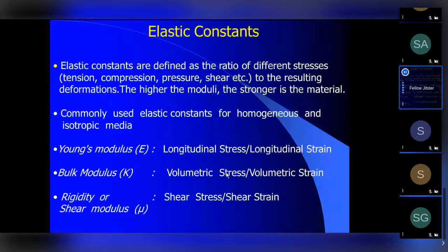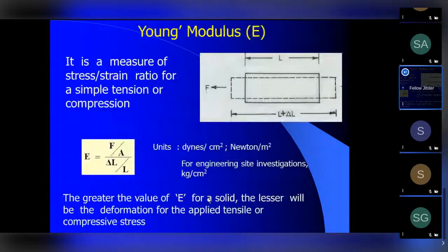I explained to you already before, the Hooke's law. So stress, it's only the different type of stress. So Young's modulus could be longitudinal stress or a compressional stress divided by compressional strain. Bulk modulus always has to be volumetric stress by volumetric strain, and shear modulus is shear stress by shear strain. So we'll see the diagrams. Okay. Now you look at this Young's modulus.